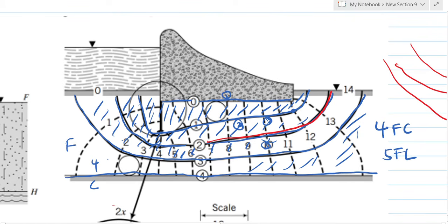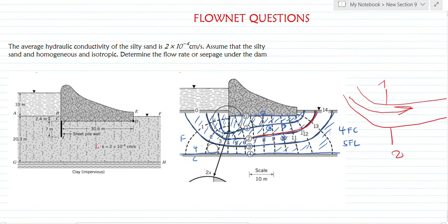You get it? So the flow lines are simply the path at which water can seep. So the base of the foundation can serve as one, just as I've indicated, right? Yes. So those are the flow lines. Now, mostly this is done using computer software. You input the parameters and it will design the flow lines for you. You can also do it manually by drawing it to scale, right? So that is what a flow line is.